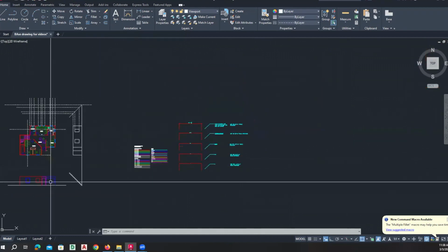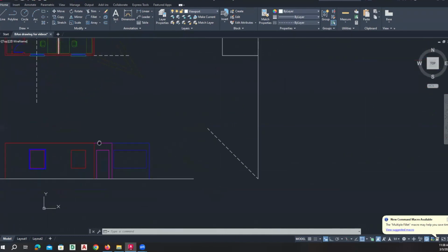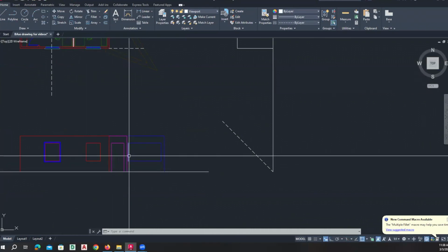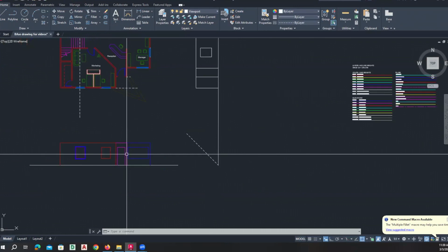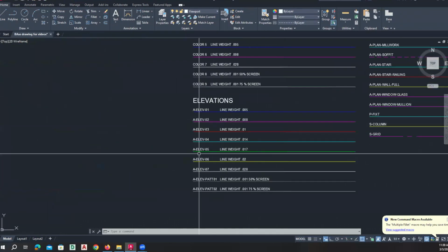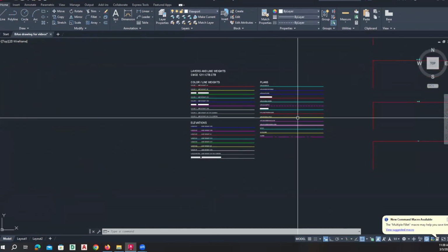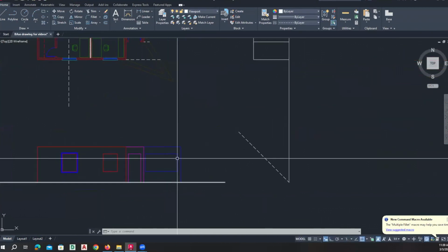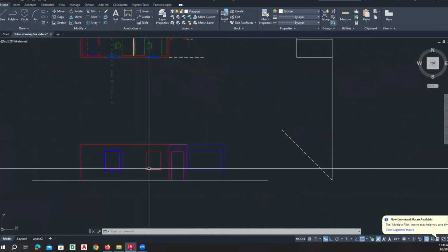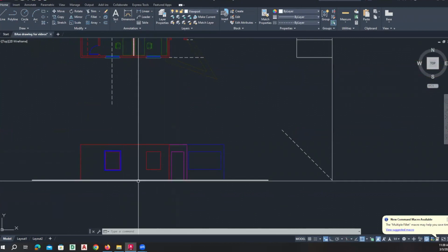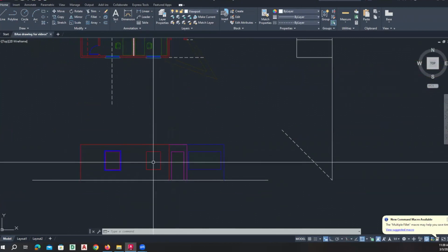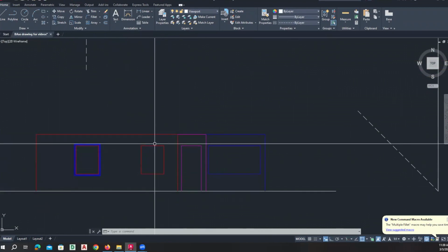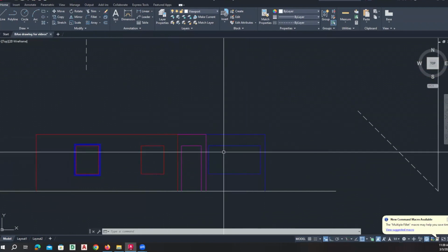So all these objects that you are drawing in elevation, be it a window, a piece of furniture, a cabinet, a wall, a door, will be on an elevation layer, not a plan layer. Okay. And so that way your drawings will look clear. They will print with the proper line weights, and you'll be able to see in the elevation what objects are closer to you and what objects are further from you.